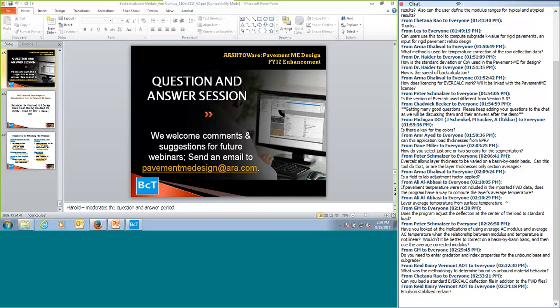The next question is from Michigan DOT, I believe, Adnan and Mike. Is there a limit to the number of drops at a single test location? The answer to that is no. You can have a large number of drops at the same test location. The key thing is to make sure you enter the target load for each series of test drops, even if they're at the same target load or the same drop height.